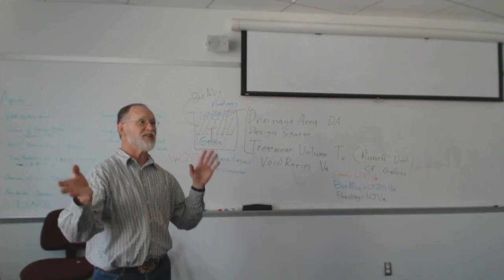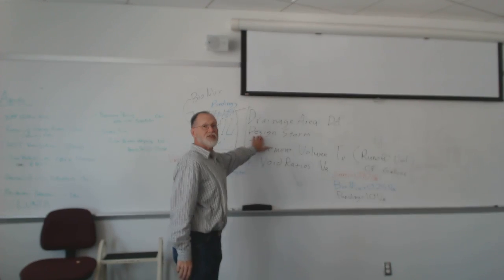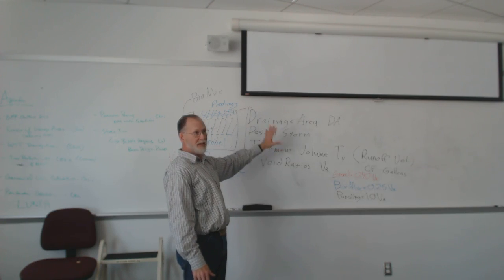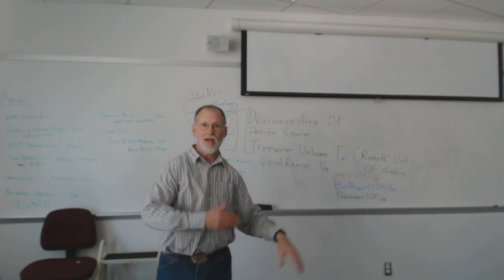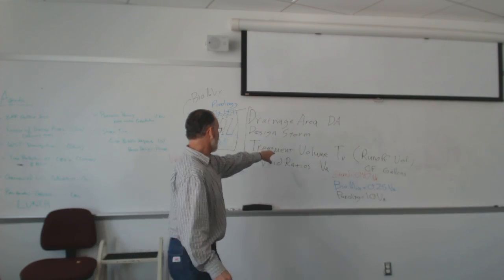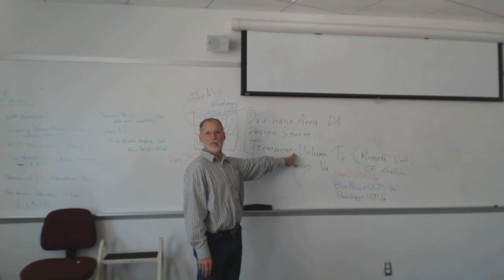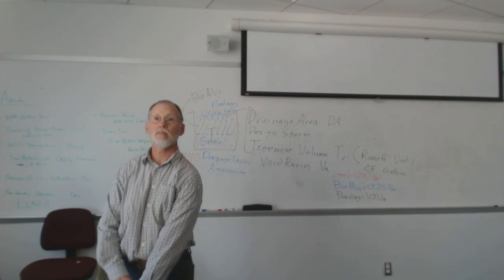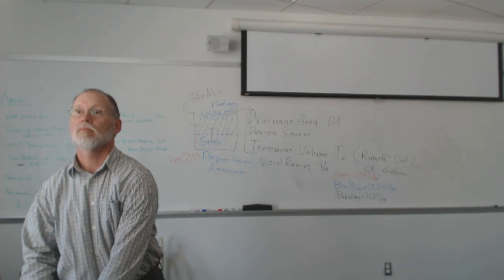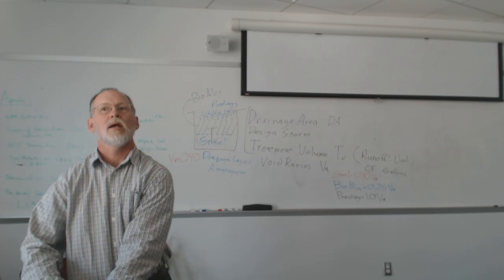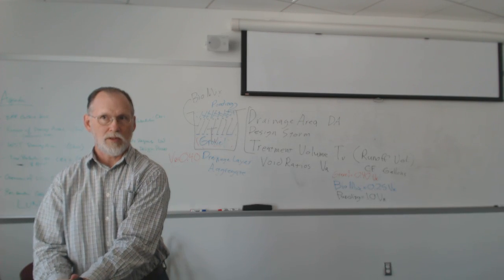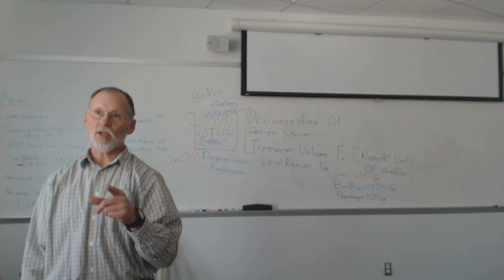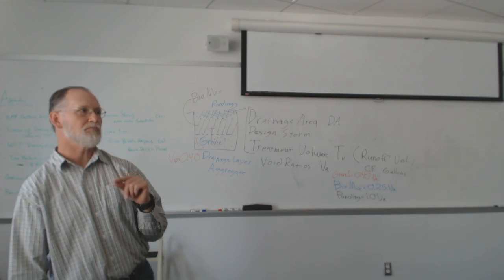But you can design these to any storm. This is just one of your variables. You can design the same features using the same methods, and all that changes is the variable you use to calculate your treatment volume. I'm asking because my city says I have to do a 10-year storm design. So do I have to look up a table for the 10-year? You can look on that NOAA site, but I'd go back and check that.